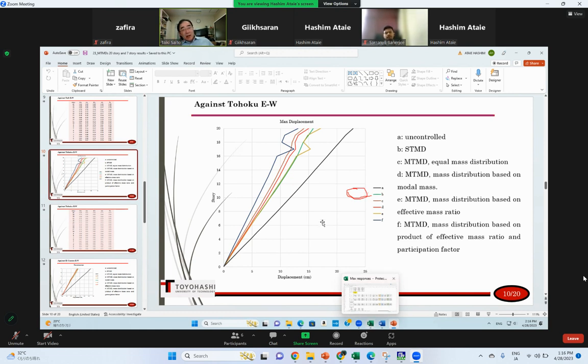Yeah, still, in case of the lumped mass model, yes, as you say, this is lumped mass, and you put the TMD height the same as the upper mass, right? Yes. That's why it vibrates. It looks more than the main building. Yeah, because the damping is lower.